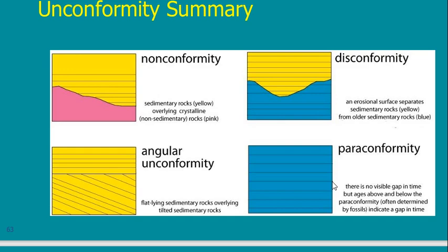This is very, very difficult to trace during site investigation or in nature, because I will find a horizontal line, but it only separates between two types of rock that are far away in time from each other. So here it needs a very specialized geologist to tell me where the paraconformity line is.